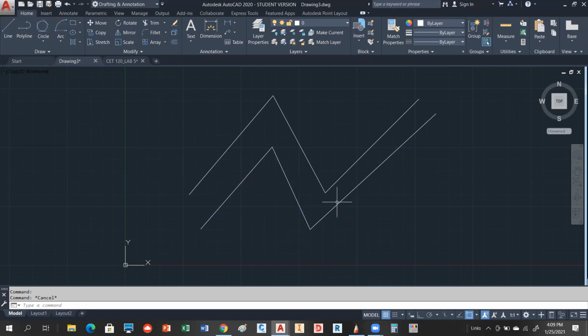And I don't know if anybody's thinking about this, but there is a way to go the other way. So if I have 3 lines, it's possible to join those guys together as a polyline. And in fact, the name of the command is join, and we'll be talking about that when we go into the modifies. So you can kind of go both ways with this.